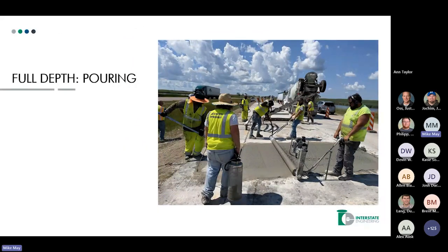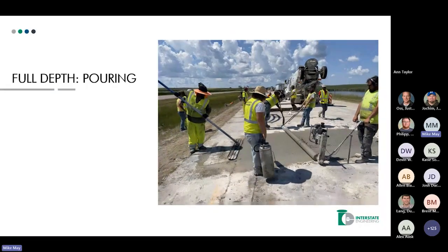And here's just a little video. As you can see, when they're doing this, you've got that roller right there. The problem we had is there wasn't enough down pressure on some of the sides of the roller. So you can see the guy way on the upper back pushing down on that handle to give a little more down pressure. Because after we started, we were straight edging and finding some deficiencies, so they had to go back. Some of them towards the end, we were probably making 3 passes on our full depths just to make sure we were getting the proper height to meet tolerances.